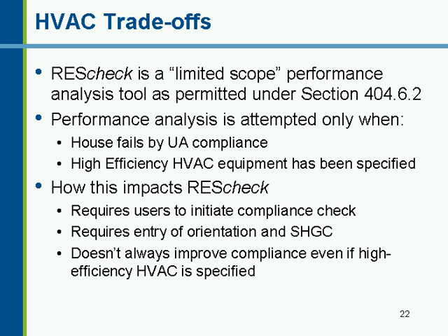And last, what is new in REScheck is the HVAC tradeoffs. First off, REScheck works the same as if your building envelope passes by UA compliance. That has not changed in REScheck. However, if your house fails by UA compliance and you have entered a high-efficiency HVAC equipment, then there are some new things that do happen. REScheck will calculate a limited scope performance analysis, which is permitted under Section 404.6.2 in the 2006 IECC.